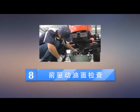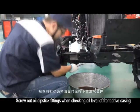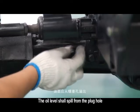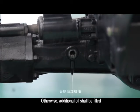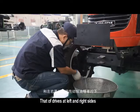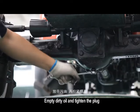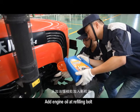8. Checking oil level of front drive. Screw out oil dipstick fittings when checking oil level of front drive casing. The oil level shall spill from the plug hole. Otherwise, additional engine oil shall be filled. When replacing engine oil, screw out the drain plug of main drive and that of drives at left and right sides. Empty dirty oil and tighten the plug. Add engine oil at refilling bolt.